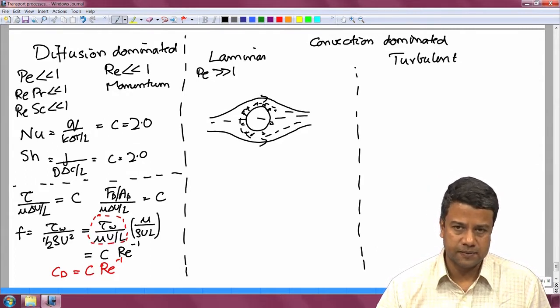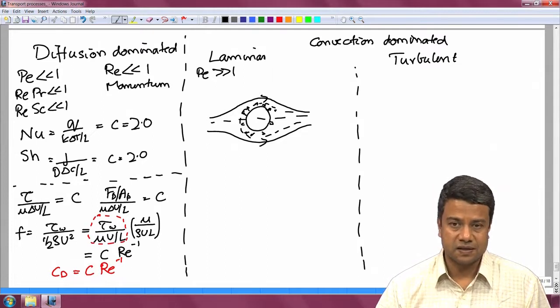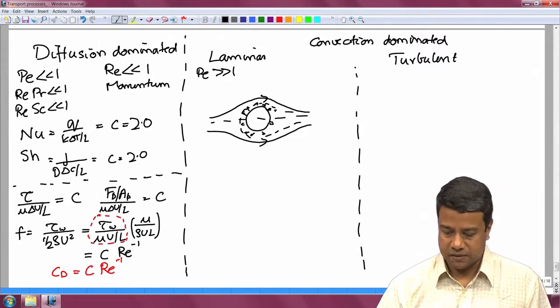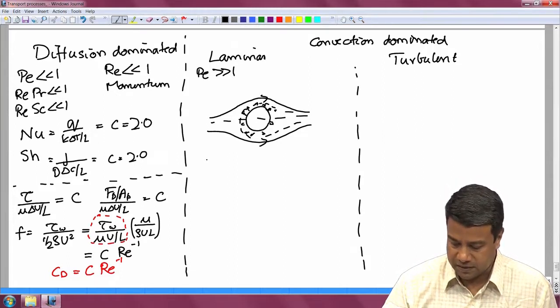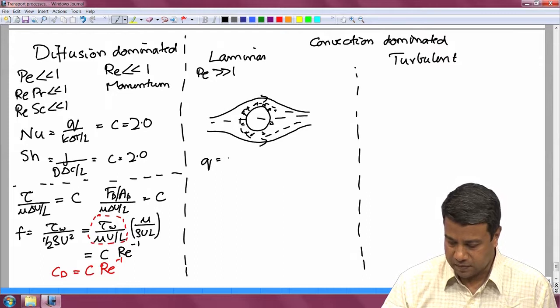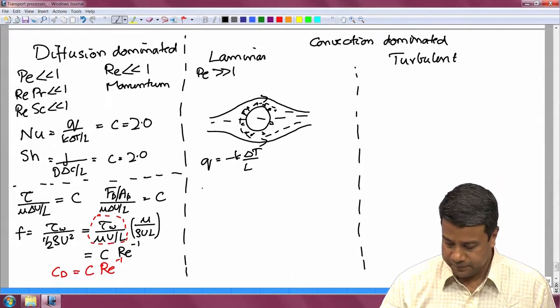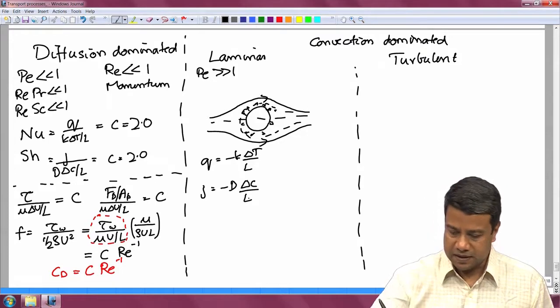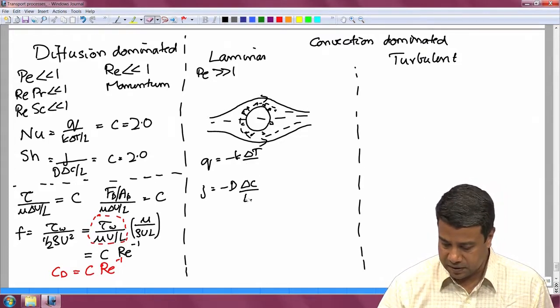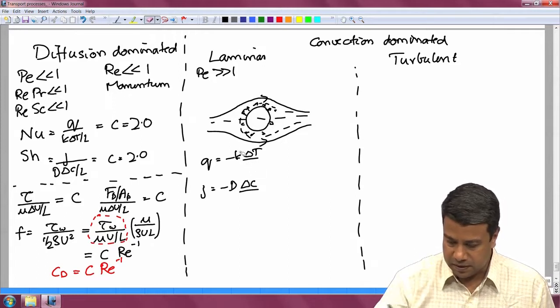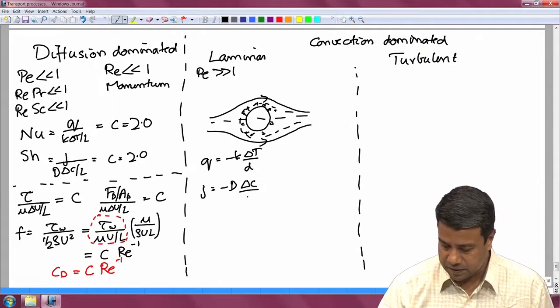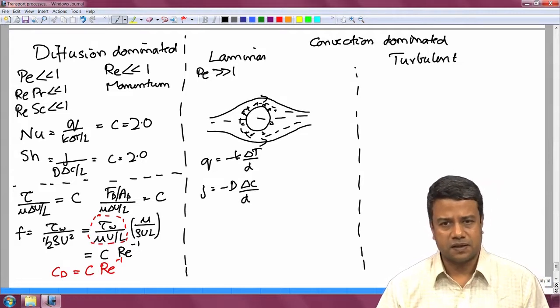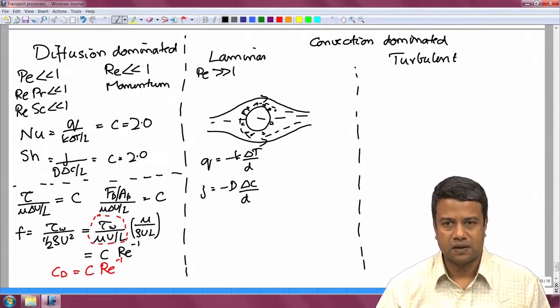It is called boundary layer theory. Because it is restricted to thin regions, if I write the equation for the heat flux or the mass flux, simplistically the length scale that I would normally use would just be the particle diameter d. You would think that is the only length scale in the problem, and therefore this is how these would scale. That is not true.